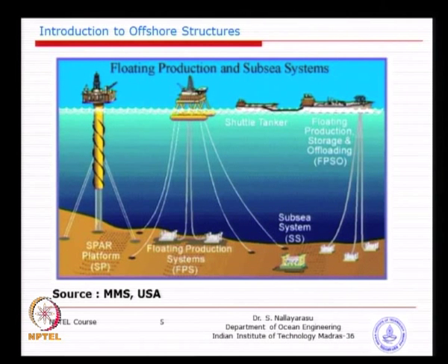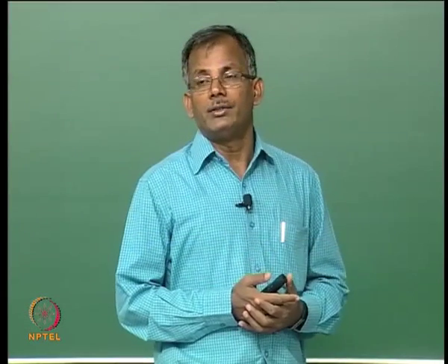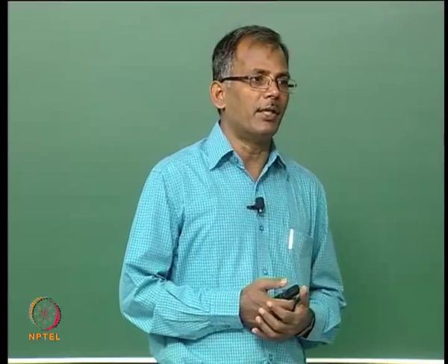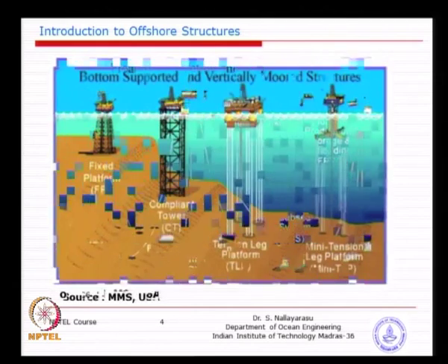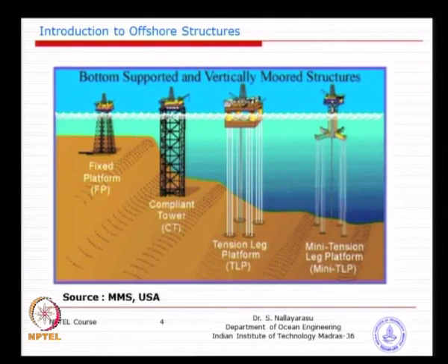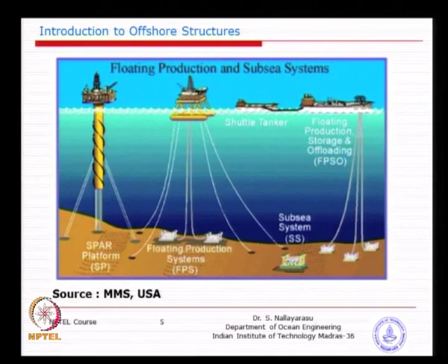So, how do we stabilize? When we go for a design, it is very easy. Basically the large mass at the top makes the system very unstable. So, what you need to make sure is that the center of buoyancy is always above the center of gravity. If you have otherwise, what will happen? Immediately capsize. Whereas, when you go back to the previous system, you see stability is automatically achieved because the legs are spread, the waterline area is smaller and the waterline dimensions are larger. So, the waterline area is smaller, the dimensions are very large, whereas when you come to this hull, both are the same and it is only a single mono hull. That is the biggest problem.